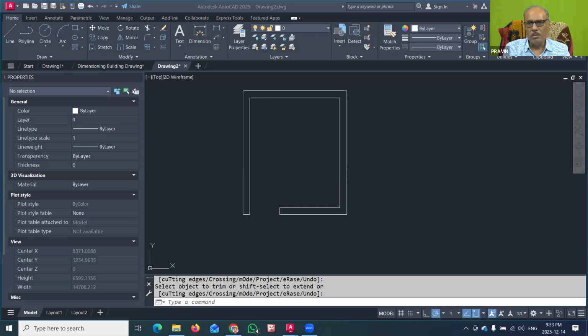So W block means converting the block into a universal block library drawing symbol, so that it can then be used universally in any drawing. So you have to remember that. I have typed that command name in the chat box. You can see that it is the W block command, but before using the W block command, there is an important step that you also have to note down.